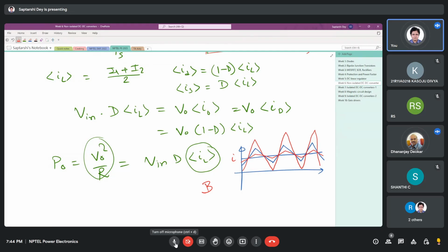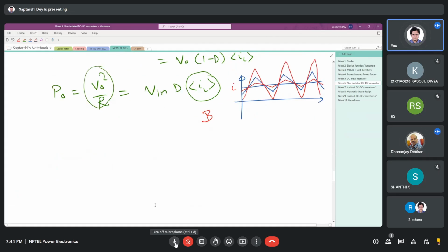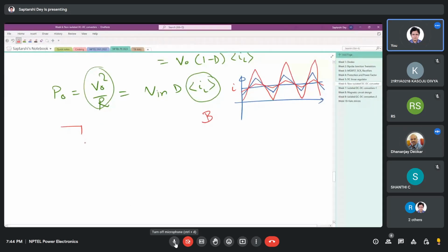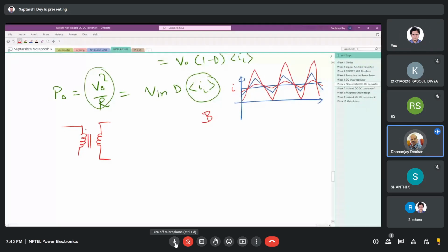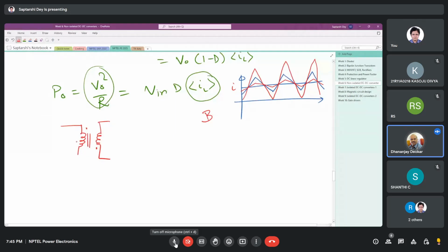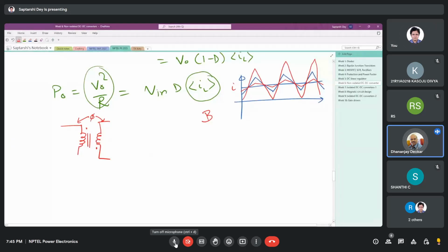But when you are talking about non-isolated DC-DC converters, I do not think you have to talk about flux. I am not saying it is necessary, but it is a very useful tool when you are studying flyback converters. At that time flux is very necessary, because that is the only thing linking the primary and secondary. We will discuss it next week. Again, the maximum B, Bmax, we have to take care of.